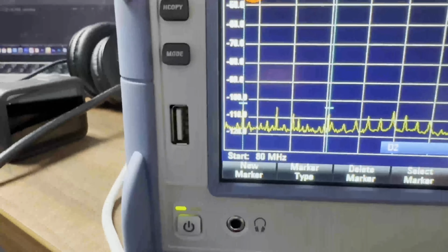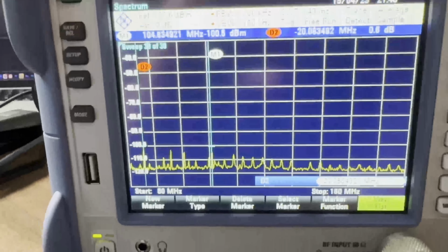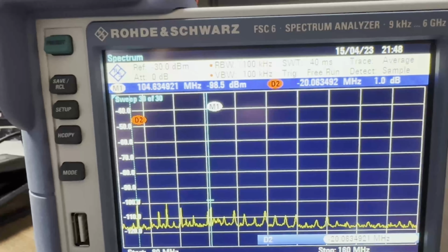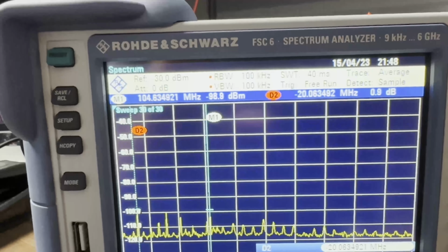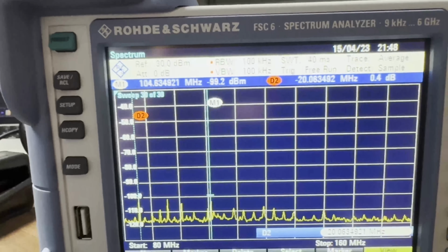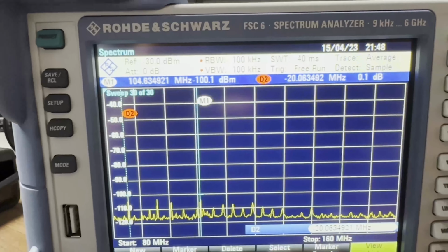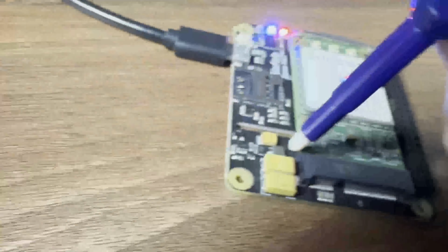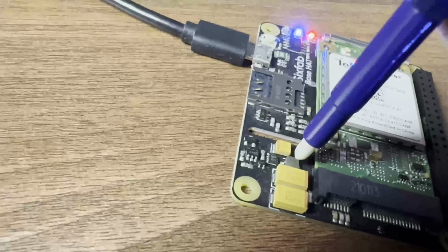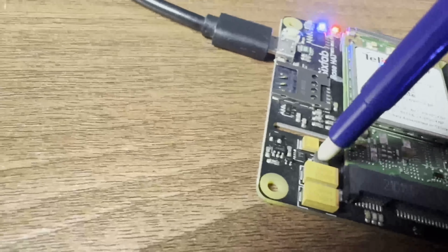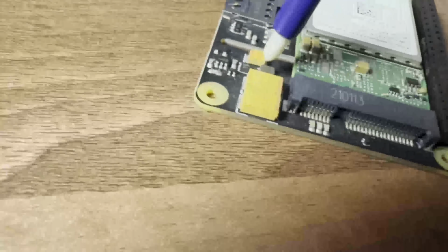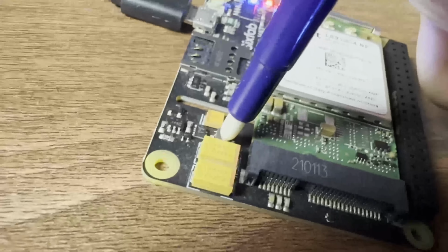Right, and you can see that. So you can see that it's changing quite a lot just as I'm moving it 1 millimeter away from this area. And this type of probe can be very useful for identifying ground plane breaks, whereas you can just go along the trace and find where the trace has got a broken plane underneath it.